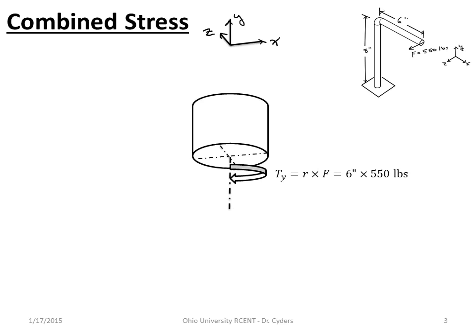So let's take a look at this torsion. We have the torsion about the y-axis that's induced by this load. So again, this load causes a bending moment down here that, as I look at this 8-inch section, is then torsional because it's around the longitudinal axis of that beam. And it's equal to r cross f. Torque is equal to r cross f. That hasn't changed from basic physics.